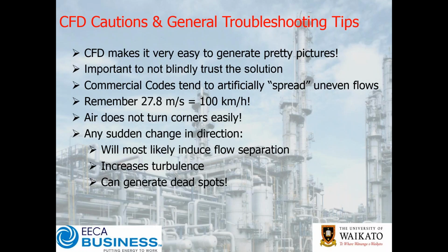Just a reminder that 27.8 meters a second is 100 kilometers an hour. Air's not going to turn corners easily, and any sudden change in direction will most likely induce flow separation. It's going to increase turbulence and will generate dead spots, and that's particularly relevant under fluidized beds and such.